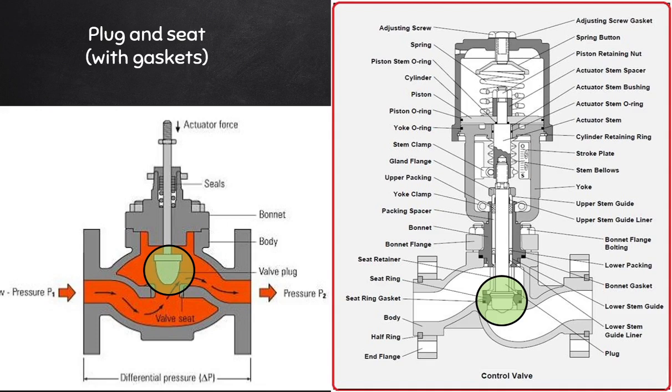Sometimes you want a valve to fail open so that a tank behind it doesn't completely flood, spilling all the liquor all over the place. Sometimes you want it to fail shut because you don't want any more reagent going to a reactor doing a reaction that then cannot be controlled safely.